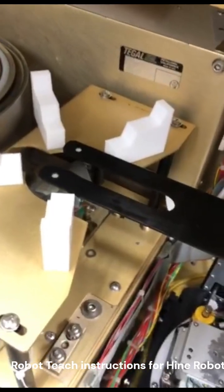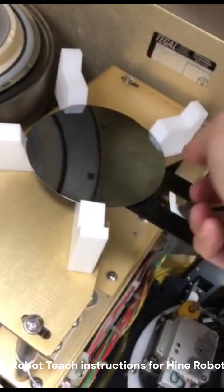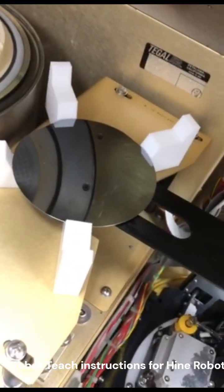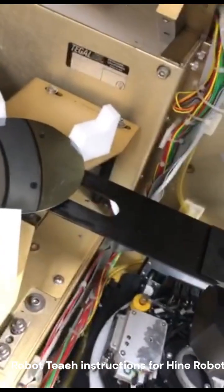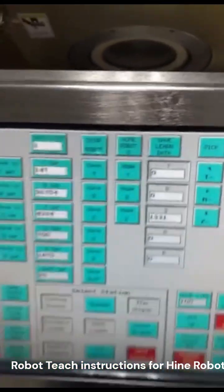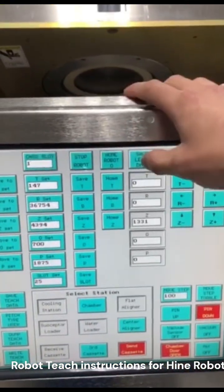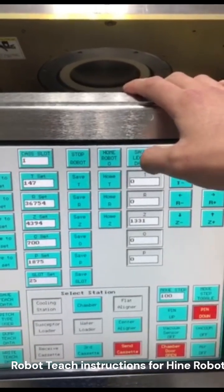Once you have that position and that it is centered, you may try to put a wafer on top and make sure that the arm is not touching the wafer. Now press Save Learn Data, and then home your robot.